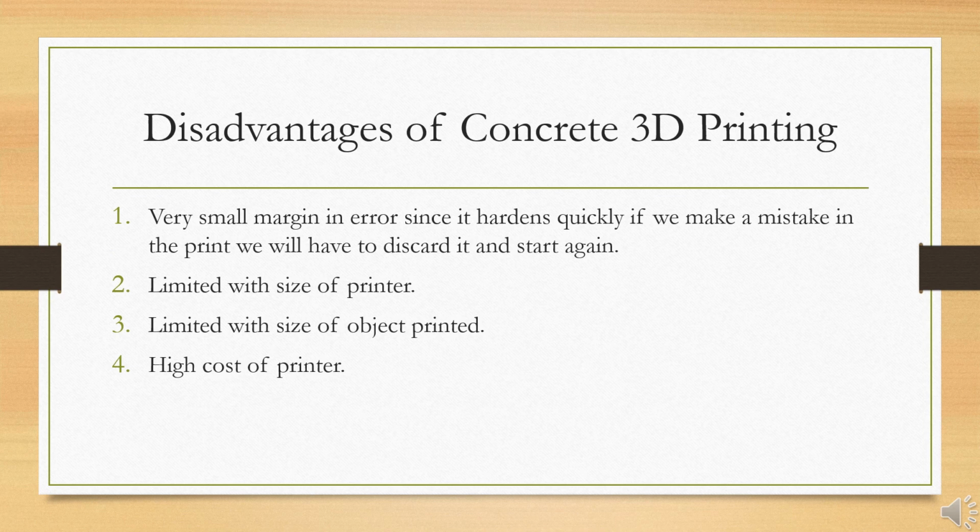Now, of course, there are also disadvantages of concrete 3D printing. Such as, for example, a very small margin of error, since it hardens quickly, and if you make a mistake in the print, you will have to disregard it as a whole and start again. The second being that we are limited with the size of the printer, and so limited with the size of the object printed.